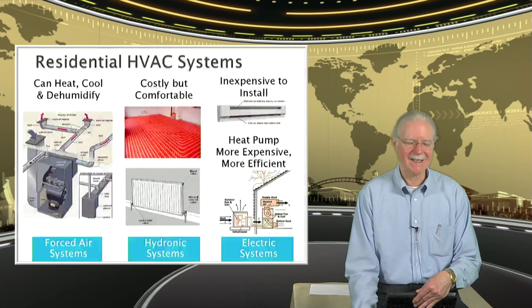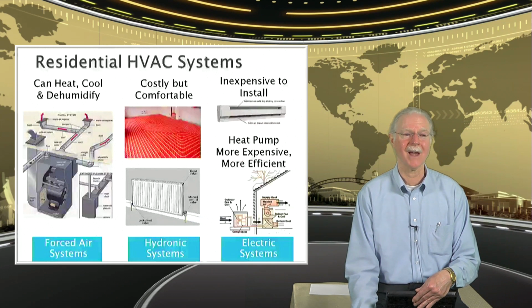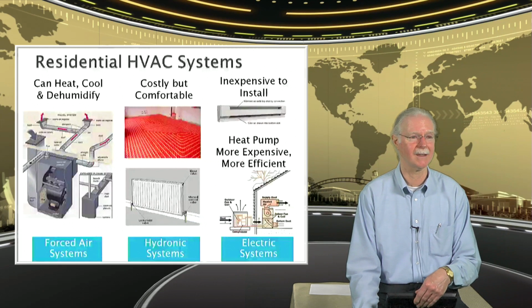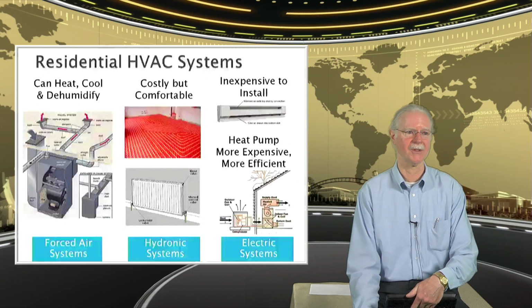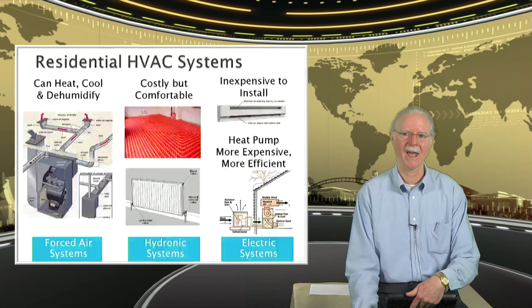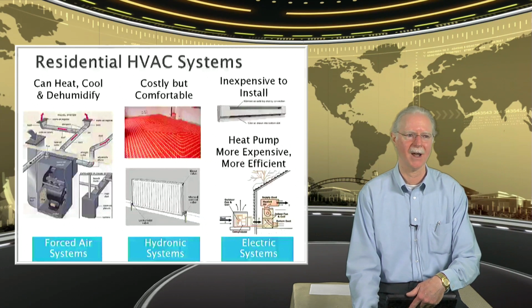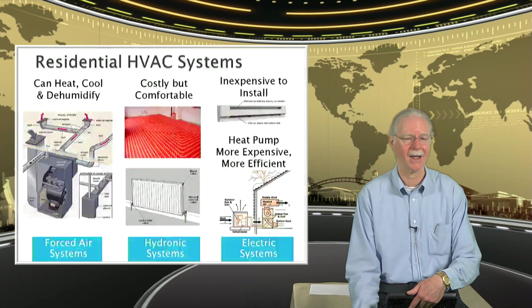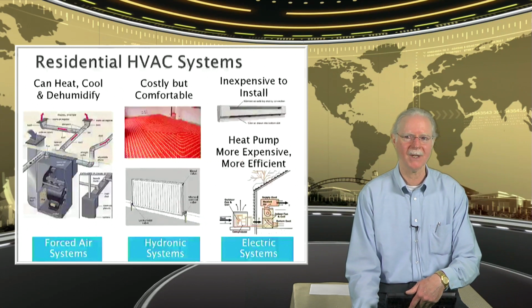There are some potentials for advantage with the hydronic systems because of that mass effect. There are a lot of ways to kill that advantage. One of them is, what do the occupants do? This is a case where, remember I mentioned temperature swings, it's especially troublesome. How long does it take for that floor slab with the hydronic coils in it to warm up and cool down? It takes a long time. So reaction time is very slow compared to forced air.